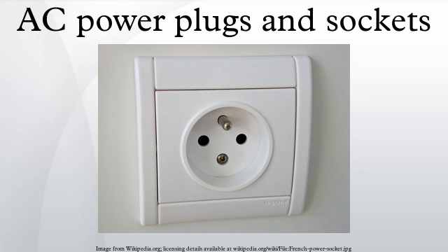There are two types of sockets and plugs in NBR 14136, one for 10A, with a 4 mm pin diameter, and another for 20A, with a 4.8 mm pin diameter, the latter used for heavier appliances such as microwave ovens. NBR 14136 was not enforced or encouraged in that country until 2007, when its adoption was made optional for manufacturers, becoming compulsory on January 1, 2010.